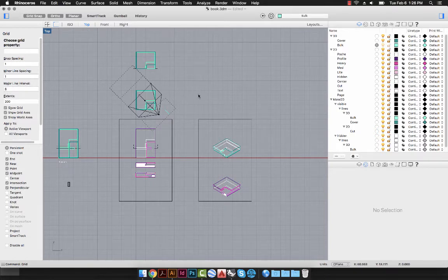So that's the 1 inch minor, 8 inch major, and I can use that major interval in order to move my objects around more cleanly rather than just arbitrarily dragging them in space. And that allows me to maintain the ability to collapse or expand my drawings as I need to. I always can use that major grid.